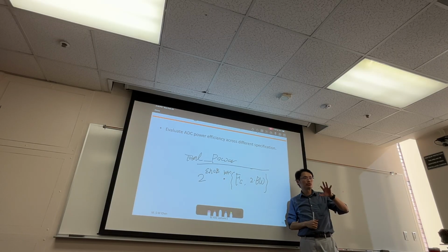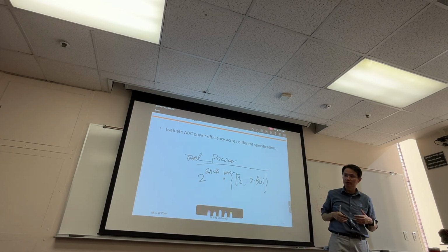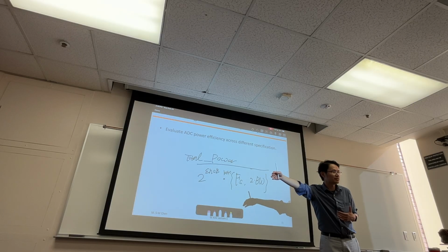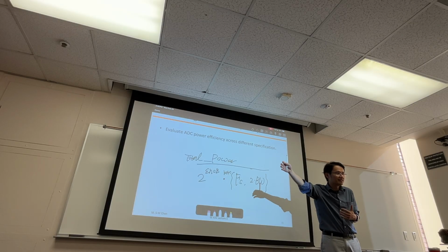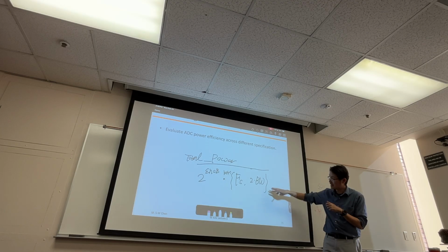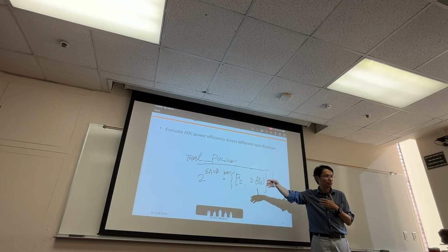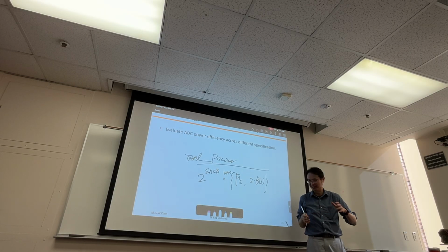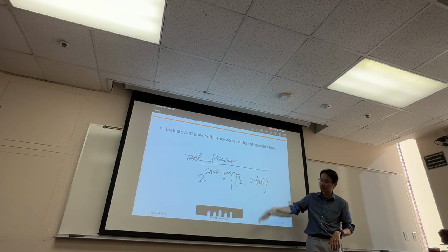So they basically try not to let you cheat, because somebody might say, oh yeah, I do oversampling, look at how amazing I am. I make the Fs 10 gigahertz, even though my signal bandwidth is 1 megahertz. But then when I normalize, I use 10 gigahertz to normalize, and you would think that I'm amazing, but I'm not, right? Because I'm cheating. I'm just having 1 megahertz bandwidth.